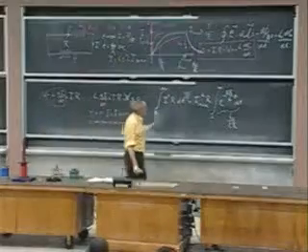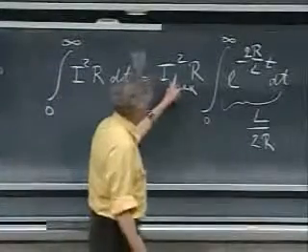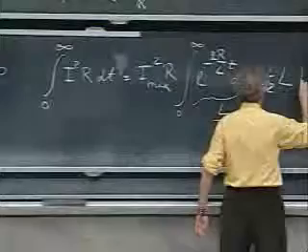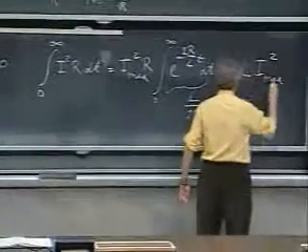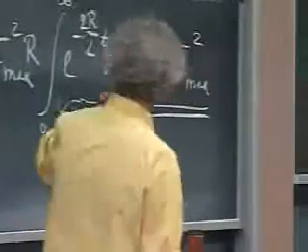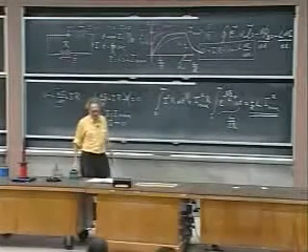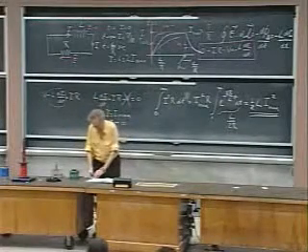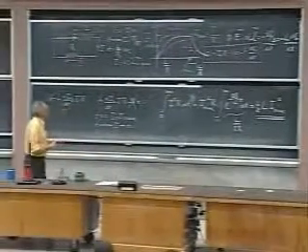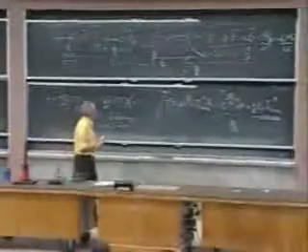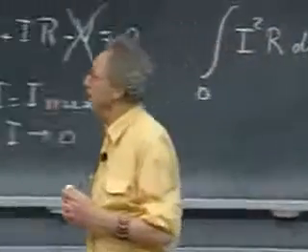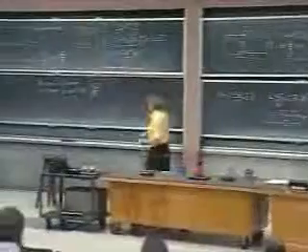And so if now I look at the product of I square maximum R times L divided by 2R, I get 1/2 L times I maximum squared. So this comes out in the form of heat. And I max is then the maximum current that we had when the current was flowing after a long time. I can now, by manipulating numbers, calculate how much energy there was in that field per cubic meter, because the magnetic field was exclusively inside that solenoid.